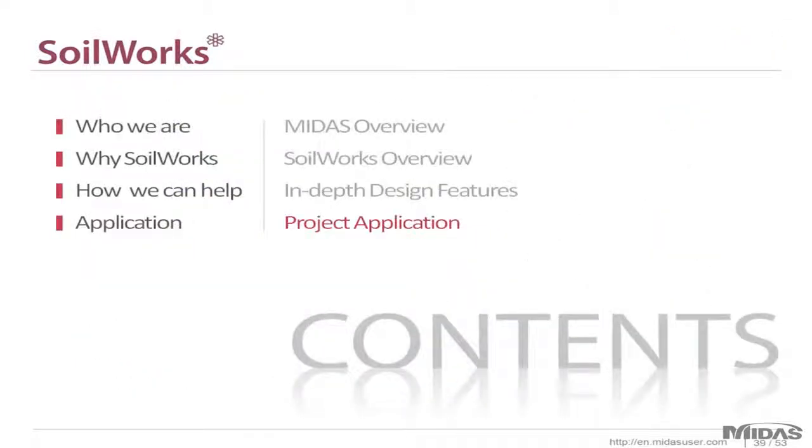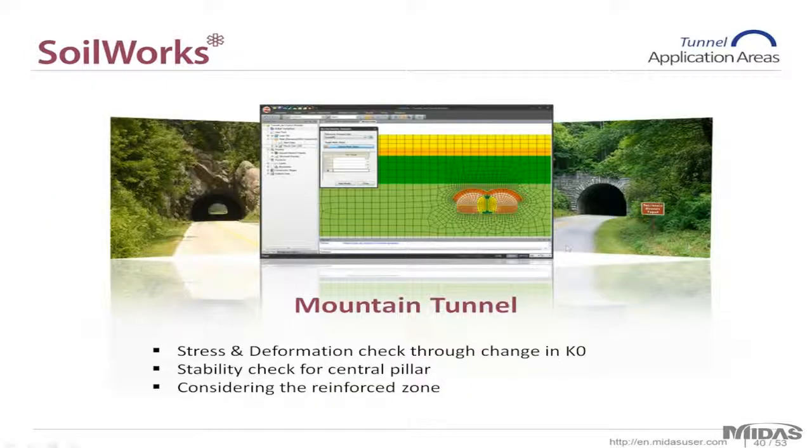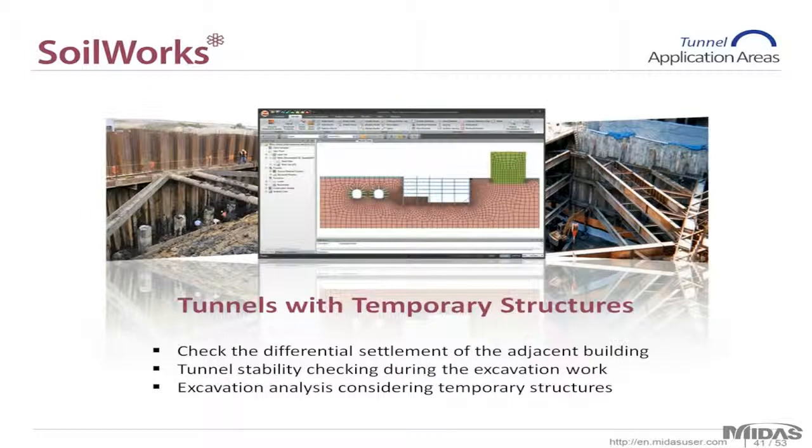Okay, so just to wrap it up, I'll go over a few projects that our software has been used for. The mountain tunnel would be an application for the tunnel module. As you can see, with the software, you can create your mesh and you can analyze the effects on the soil by your excavation or your tunnel. Tunnels with temporary structures: the tunnel module can also be used for excavation projects and construction stage analysis. So you can model the different elements that will be present during various stages. Then you can also simultaneously analyze the effects on neighboring structures from your excavation and your construction.